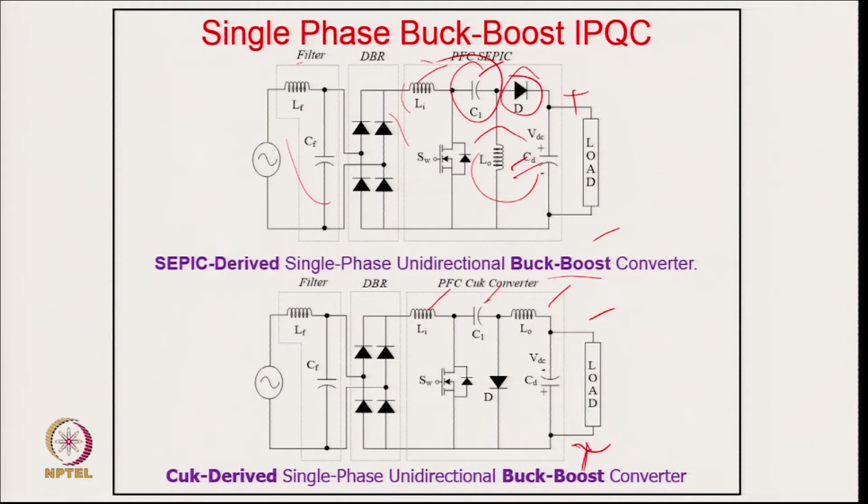It is also called a noiseless converter, as it should not have noise, so the inductor current should be almost constant at the input and output. Of course, in CCM you can operate in that mode also, but the size of the inductor will be substantially large. So people, even the Cuk developers, had not thought about how this converter would be operated for different applications now.